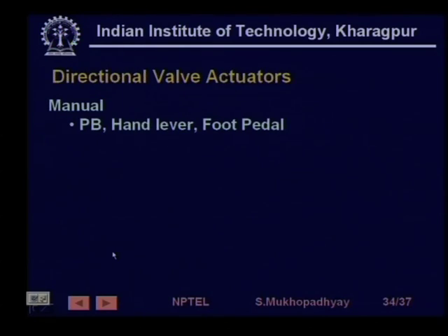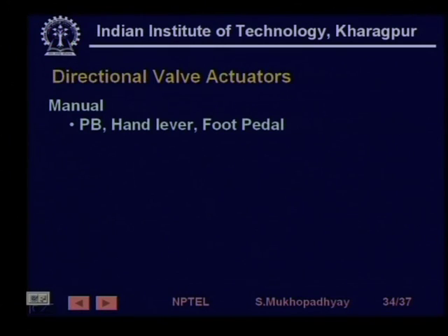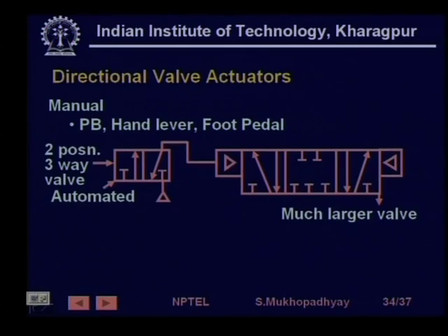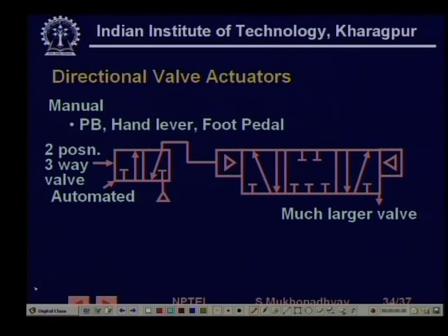These directional valves, sometimes they have to be moved. We were talking about moving the directional valve from this position to that position. So, how do we move that? As just like in hydraulics, there are various ways. You can have manual, where you can have a push button, a hand lever, a foot pedal, whatever you have, or sometimes for very large valves, you can have a pilot valve.